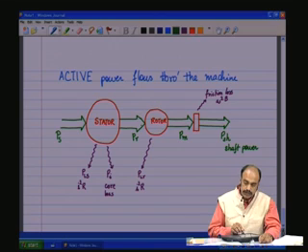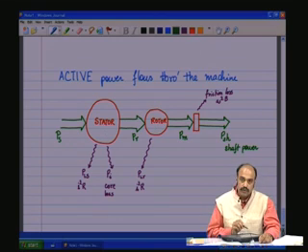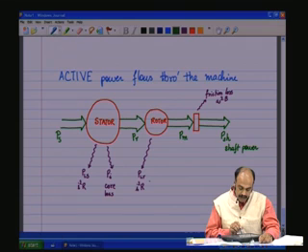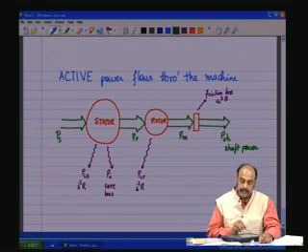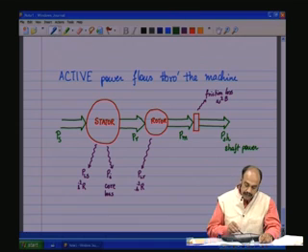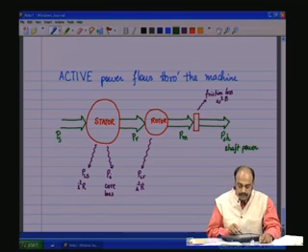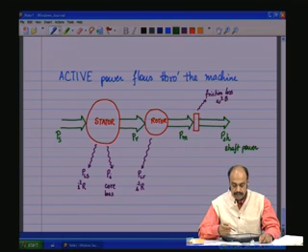Then the remaining portion PR enters the rotor, and some amount goes off as the copper loss, PLR, I square R loss due to the rotor conductor resistance. The remaining power goes as PM, and out of PM an amount B omega square goes off as friction losses in the bearings. The remaining power is the shaft power, which goes to the load.